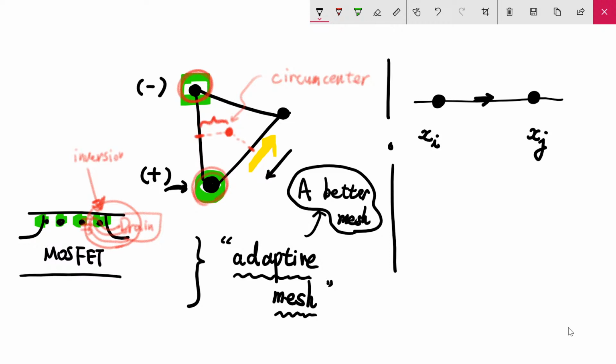So usually they just make a mesh. And if they have certain problems like accuracy problem or stability problem, meaning a convergence problem, then they find that their mesh is too crude and too coarse, find out some points where problems occur, then try to remesh those localized points again. Then in many cases it improves the accuracy and also the stability.